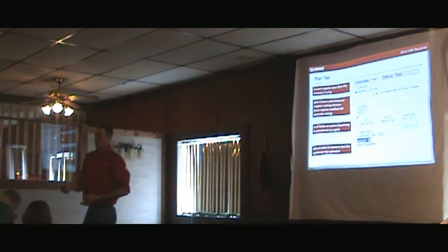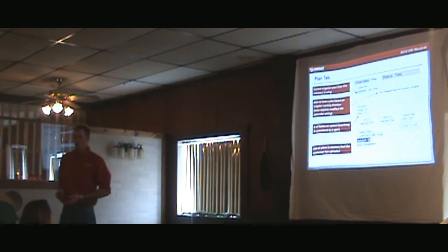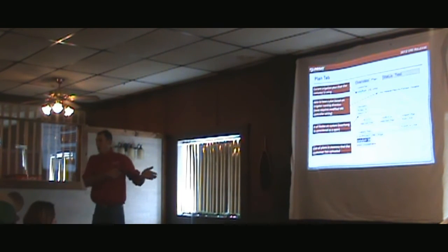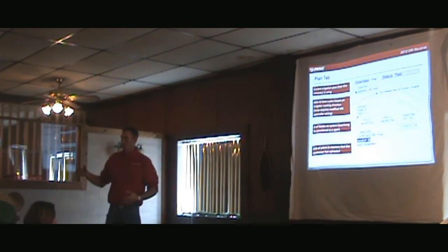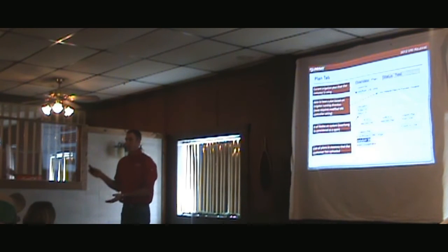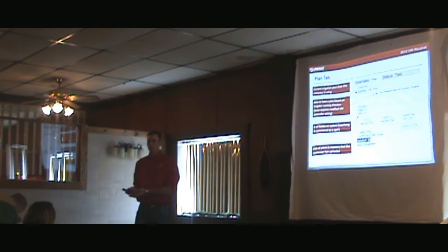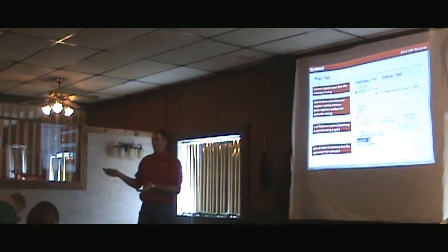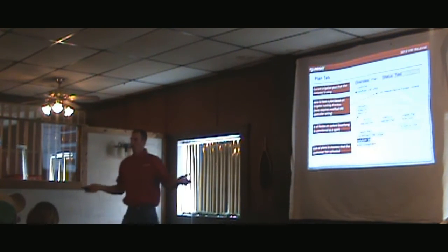Let's talk about fertigation for a little bit. I've had guys say, well, I want to use VRI to do a variable rate fertilizer application. Correct me if I'm wrong, but you can do that just by pulsing and putting the different rates, and you have a static concentration level of water. This particular guy was trying to have a variable rate injectometer as well as do variable rate water application. But in my mind, that becomes too complicated and you have two moving targets and you can't match that. If you want to do variable rate nitrogen application and you have a VRI, use a static injectometer.